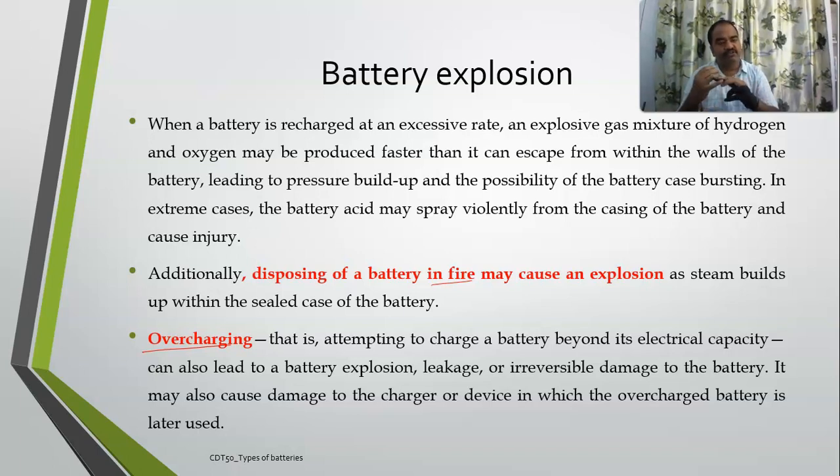And the rate at which you charge is also one of the most important things, because recently you are getting explosions. At any cost, what I mean to say is that it's not only the current. You must monitor the charging current, whether it is in prescribed limits or not. And you should handle it properly when you are disposing it. And you should ensure that there is no leakage from the battery. And finally, you ensure the operating temperature of the battery. All these factors do affect the battery explosion.